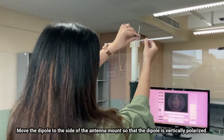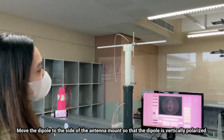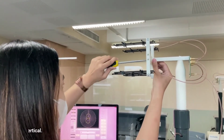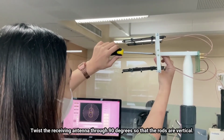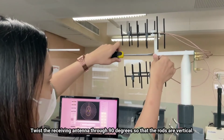For the second part, move the dipole to the side of the antenna mount so that the dipole is vertically polarized. Twist the receiving antenna through 90 degrees so that the rods are vertical.